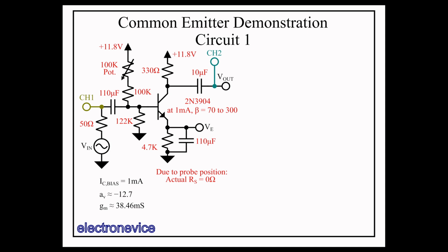We're running this circuit around the 1 kHz to 10 kHz range, and so I'm connecting these signals directly to the scope using effectively a 1x probe rather than a 10x probe. Additionally, I'm triggering the scope using its trigger input and a TTL output that my function generator outputs alongside the main signal. This produces an extremely reliable trigger, allowing me to use a combination of the oscilloscope's averaging function and its digital filtering to clean up the signal even more so that we can see it clearly.